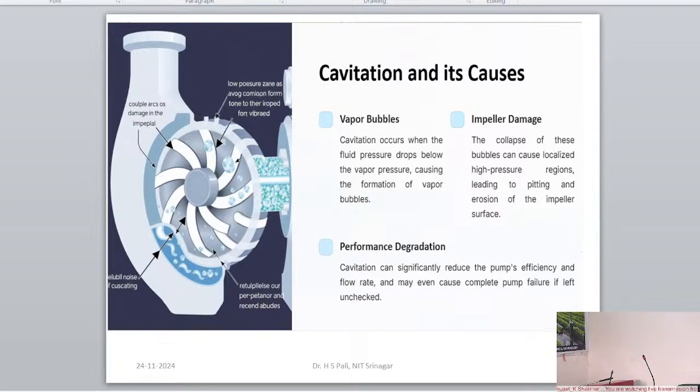And then plot this on a graph. This will represent it. You can see the video here. The flow rate is increasing, the head is decreasing. As the head decreases, the flow rate increases. The performance curve will be different for each pump, and some will suit our system needs better than others. You will usually see that as the pump flow rate increases, the head pressure decreases. When selecting a circulating pump, the pump will only perform as per the line. So, for this model, if we wanted 8 gallons per minute, then we would have 6 feet of head.